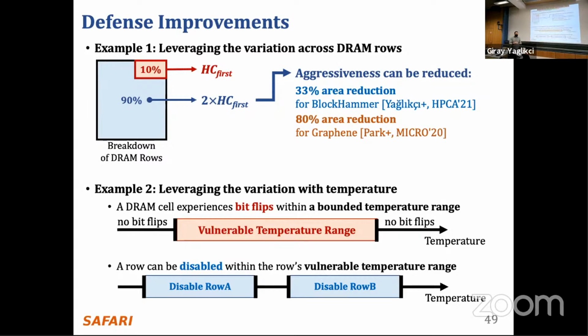And probably you know that there are redundant rows for improving yield in this bank, right? Or you can maybe just reduce your usable address space, and you can swap in, swap out some DRAM rows based on what temperature you're operating at. And by doing this, you can actually make your whole system more reliable, basically.